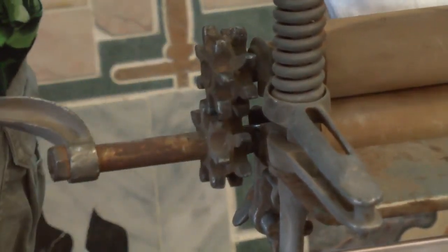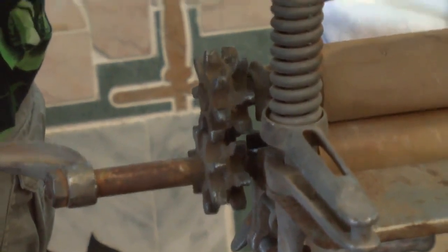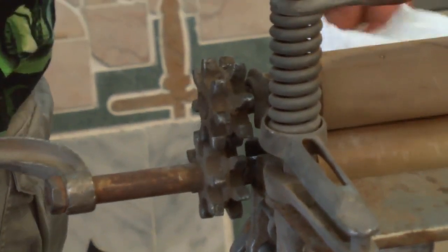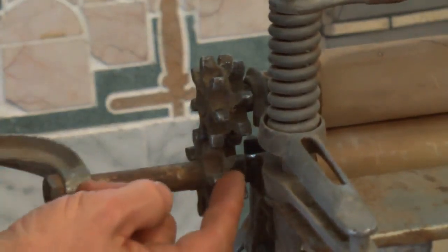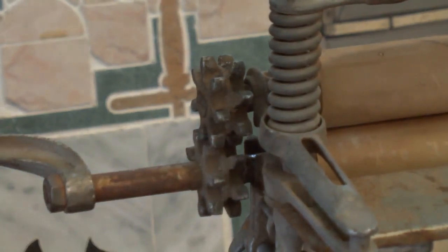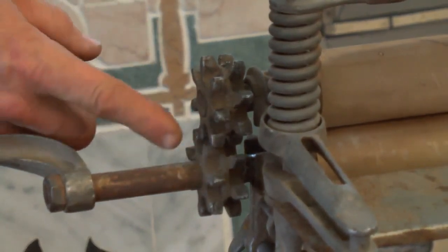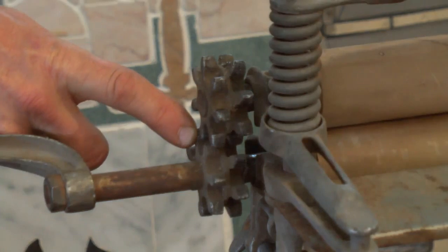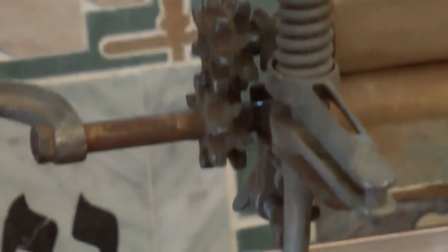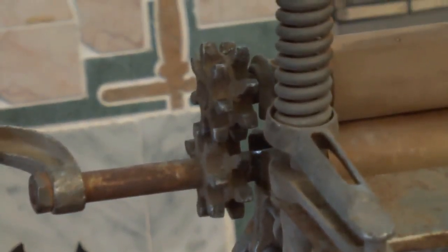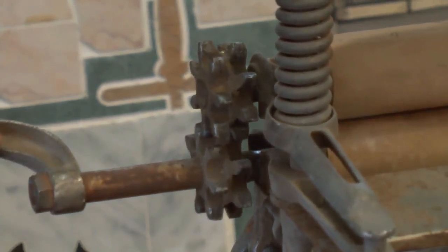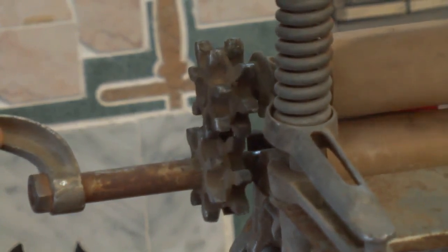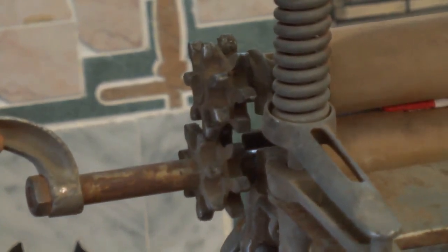If you look on the ends, before I engage and suck the cloth in to wring it, there's a certain amount of overlap between the gear teeth. And also be looking at the other two gear teeth on the inside. As the outside layer of gear teeth just start to engage here, the inner set will not be engaged at all. And when I start to rotate this, see when it first engages, there's hardly any tooth contact. And you think, oh my God, look at that, it's not engaging at all.